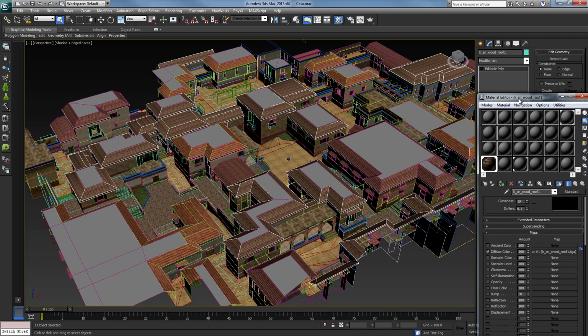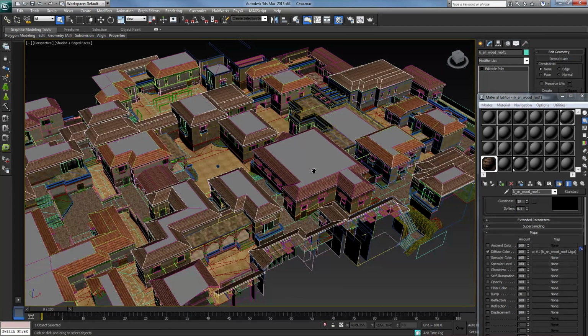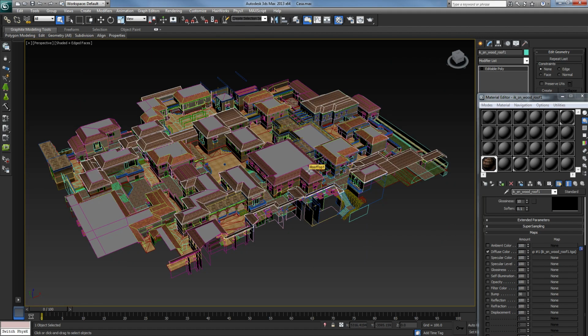So this way I create a connectivity between the material and the object itself. Once we start breaking things down, I'll do a bit of a lecture on that in just a minute here. Once we start breaking things down into blocks, it becomes a lot easier to maintain a direct connection in Unreal 4 as to the material that is connected to what object. So once you start breaking things down, it maintains the material ID, and you're not having this problem of every time you import a new object, you're getting duplications of the different types of materials. So once we establish this, we've more or less locked our material into the object itself, and we're good to go as far as moving forward.